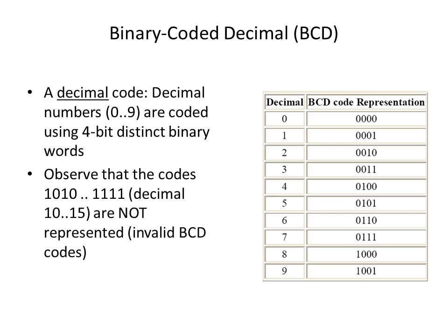How is binary coded decimal represented? In binary coded decimal, there is a table from 0 to 9 with the BCD representations. 0000 are 4-bit codes. These are 0001, 0010, 0011, 0100, 0101 and so on. But here 1010 up to 1111, that means 10 to 15, are not used for BCD codes. They are invalid codes.